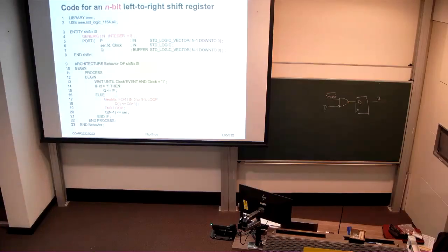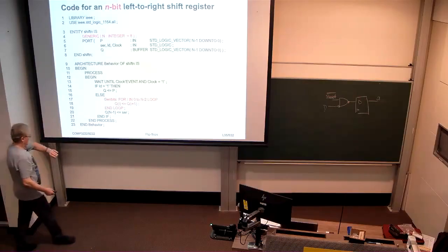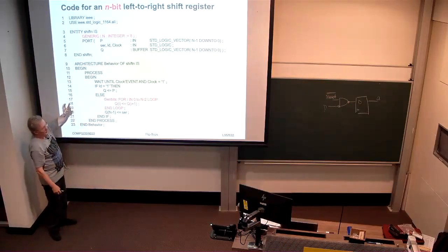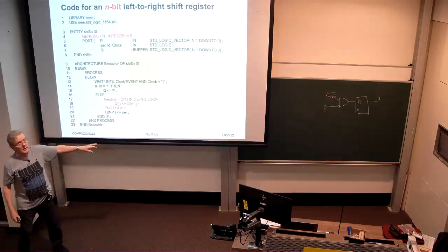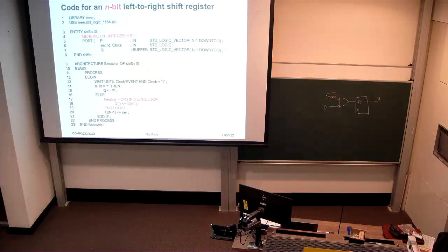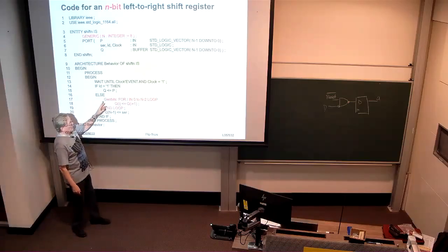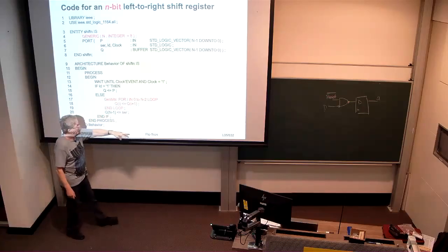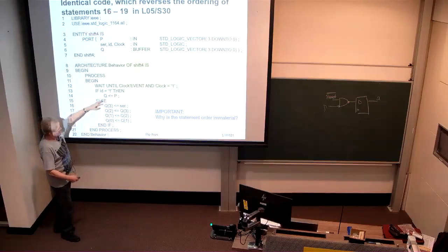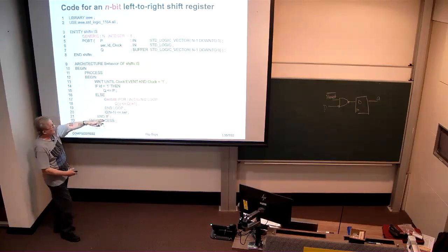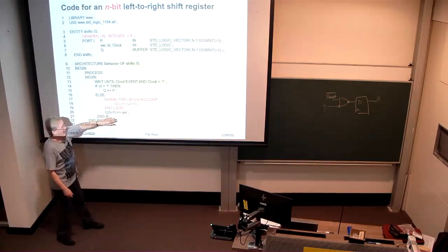I think I have one more slide for you to be swamped by. We saw last week the for generate statement, which acts effectively as a macro to repeat several combinational statements or instantiations. The corresponding syntax for behavioral synchronous sequential statements is the for loop statement. So just as we saw on the previous slide, several assignments here to Q means exactly the same.